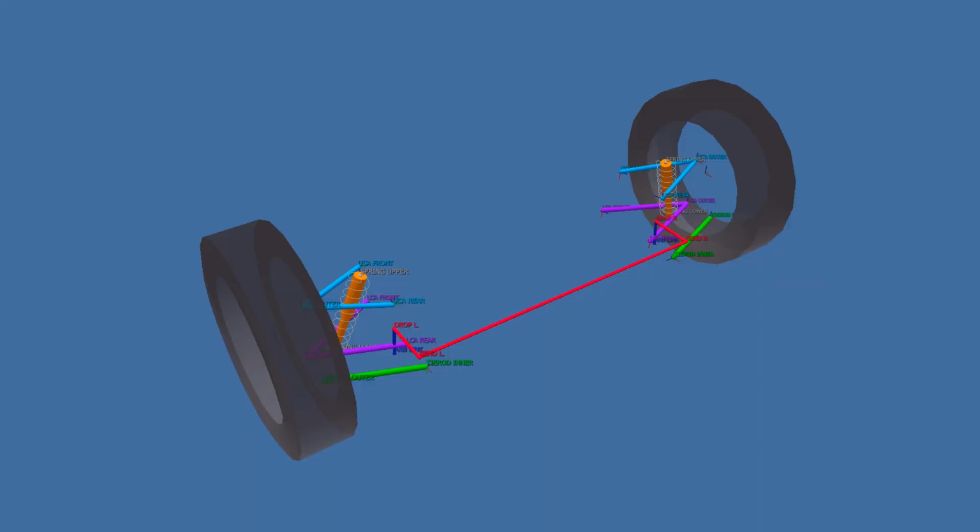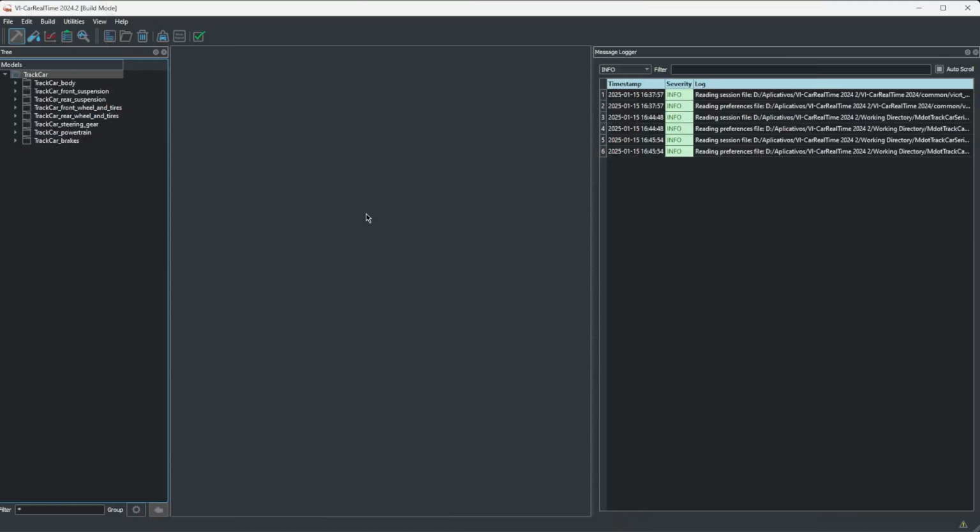In most cars, the chassis hardpoints are deeply connected to the structural design, and we will avoid changing them. What we will do is focus on adjusting the outer hardpoints, the ones on the upright, because doing so allows us to act on all of the factors we need while only requiring the redesign of the suspension arms and the uprights themselves. Luckily for us, we don't have to worry about compliance, because the original sports car suspension already came with rigid joints that we can keep in our updated design.